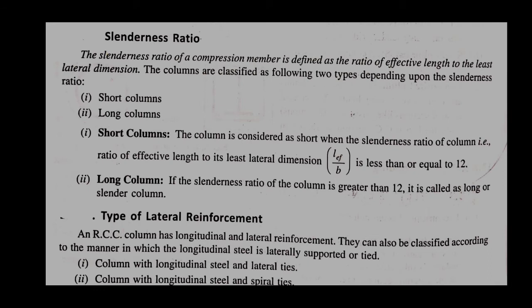Here on your screen you can see table number 28 of IS 456 2000. Look at the extreme left, there are the support conditions, after that the symbol of support condition, and there are the values.